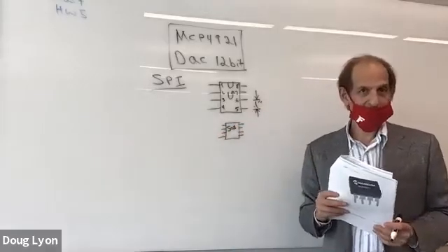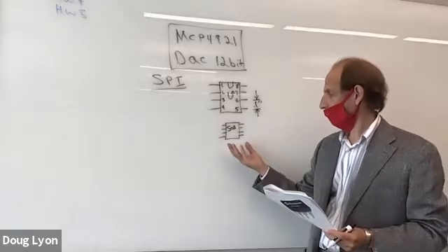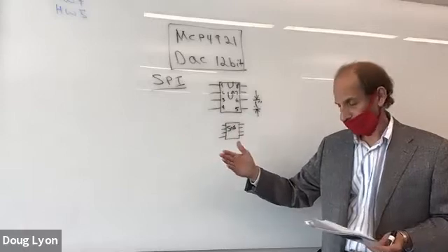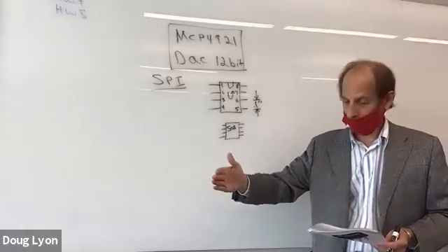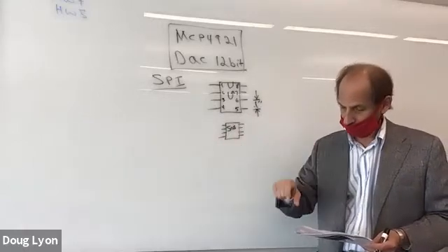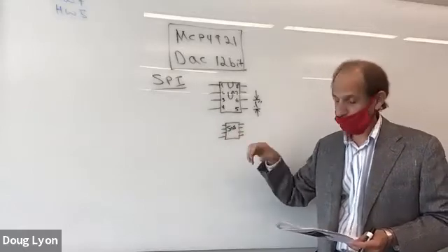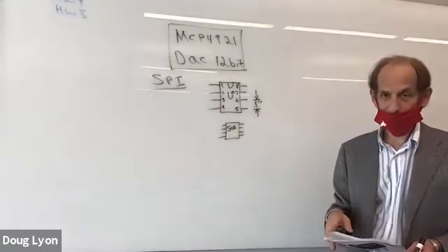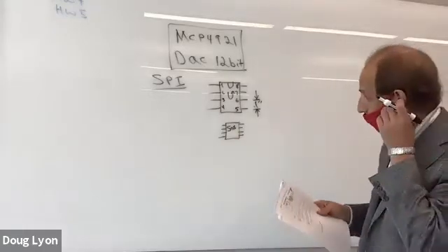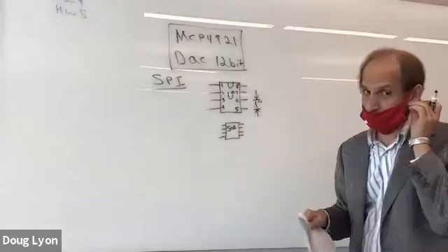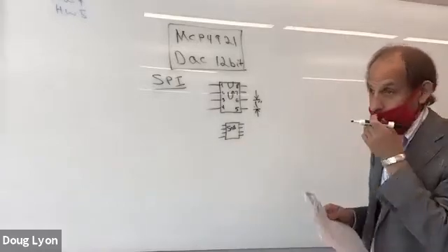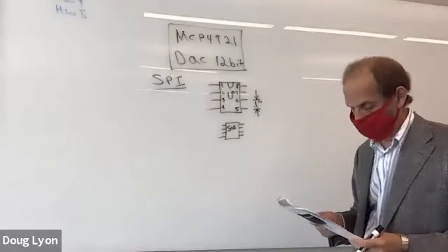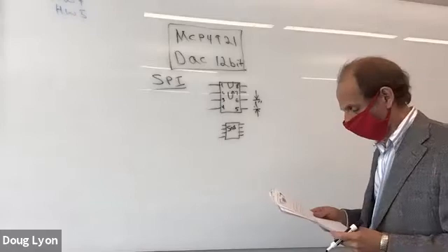And that is a standard which you can use for so-called surface mount technology. And what you'll do is you'll get something like a stencil or a machine that can lay down some solder paste, and you'll place the chip onto the solder pads and then run it through the oven, and it'll just solder them all up and you won't have to drill any holes at all. The pick and place machine will shoot these things out like a machine gun. And they'll do it on a giant panel full of boards, and then you'll have a whole bunch of boards being made all at once.